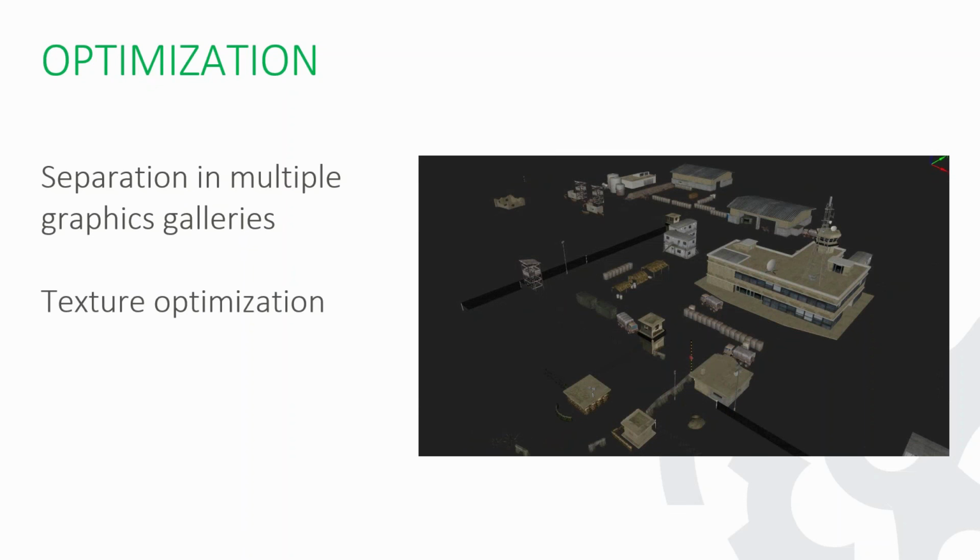The texture optimization: basically we went all with models that were featuring fairly high-level texture. Once we went into the driving scenario, we took notes of what's available and what's visible from the truck cabin, and objects that were further away from the truck were noted down. Then we went back in the graphic gallery and reduced the size of the texture to reduce the memory footprint.